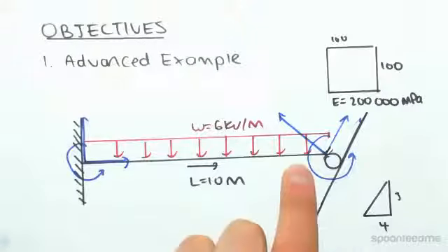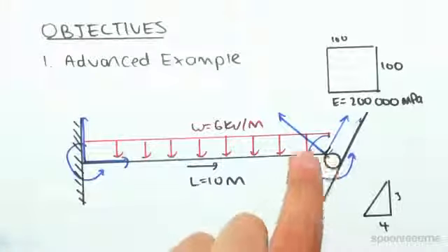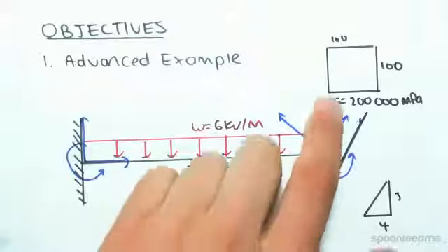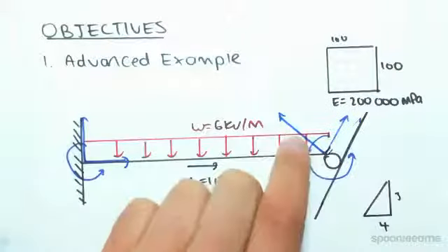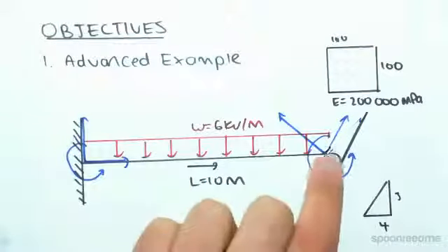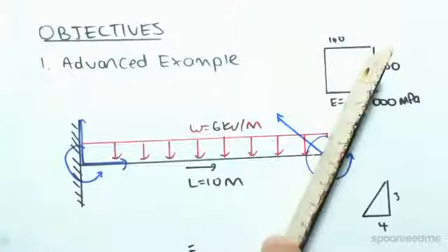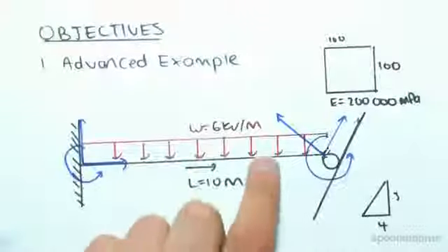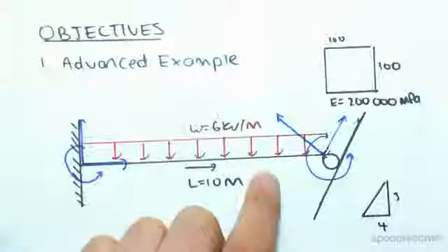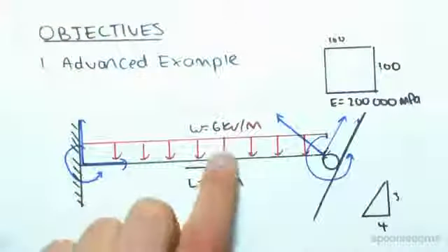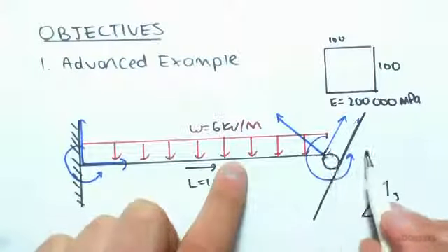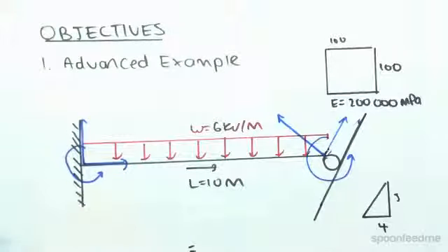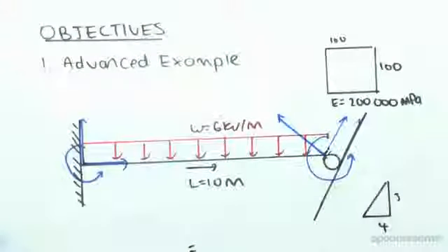But just for now, I want you to realize that when you draw your degrees of freedom, they're always in the global degrees of freedom. So this is the global axis, as we always do. The global degrees of freedom are always in reference to the node. So the node parallel is there. The node vertical is there. Okay. The local coordinates are always in terms of the actual member. So if we had this member here, the local coordinates would be right and straight up. Okay, so we're doing global coordinates though, as we always do. Now we're going to label the global coordinates as we always do.